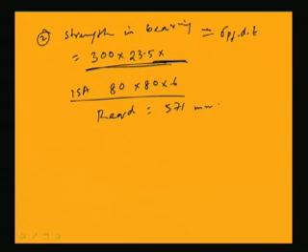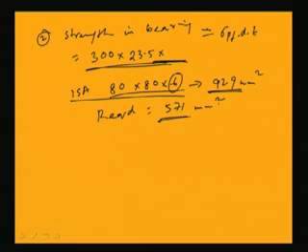Okay. And this area is given as 929 millimeter. Okay. So, required area is 571, let us use 929 millimeter square of area, where the section is 80 into 80 into 6. So, the angle thickness is given 6 millimeter. So, if we use 6 millimeter, then we can find out the load.